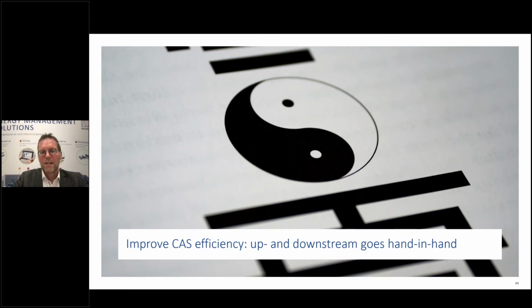And so the demand side already gives you a lot of information on basically how well the whole compressed air system is performing. And you will also find out that when you start to fix things in the demand side, it will also affect the supply side. So the compressors start to run differently. The controls sometimes need to be adapted, and sometimes you can just turn off a compressor when you have fixed enough leaks.